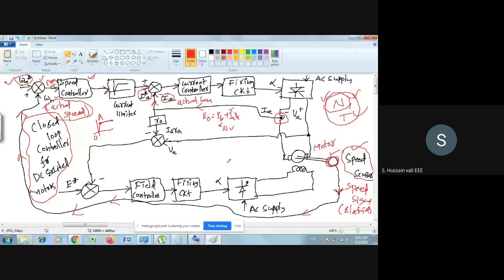This is the symbol. Now this symbol, I will tell you, is for current sensing. Even you can search in the books, you'll find this symbol as current sensing. So you sense the current from this line. Just now I have shown you a picture of the current sensor. There you find a hole, this black colored hole. Through that hole the wire goes. Then the output of that sensor will be sensed here through this line.